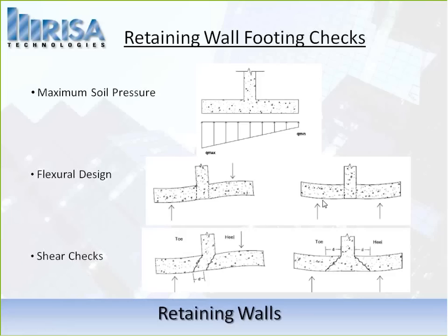The shear checks there are going to be done for the footing, and this is the same kind of check we were looking at before, in a different direction with that d distance away from the edge of the footing there. So you see the program's going to check that in each direction based on what type of loading is going to be in this footing. Depending on which way is going to be the critical direction, we're going to find that appropriate location for you. So the shear, we've got a rundown of all the different checks,